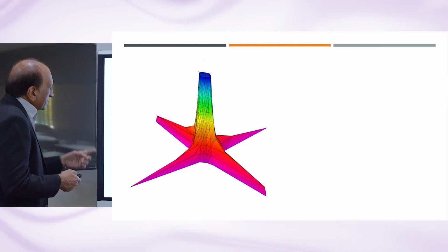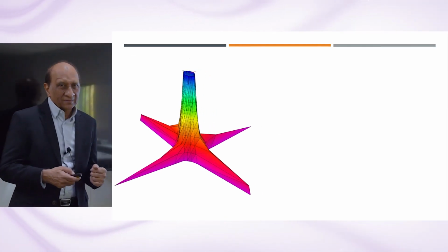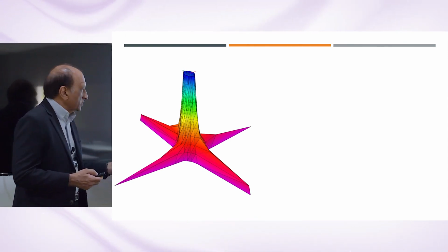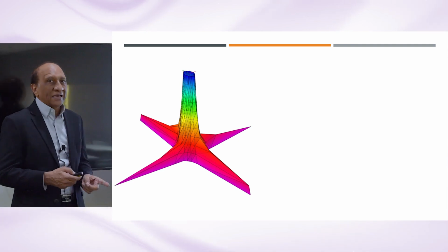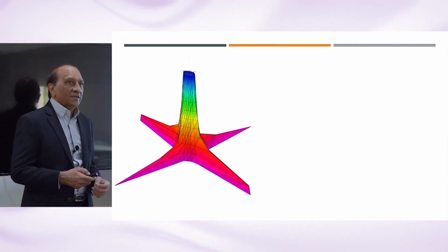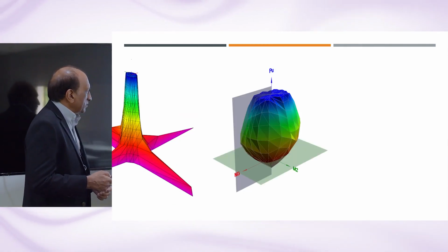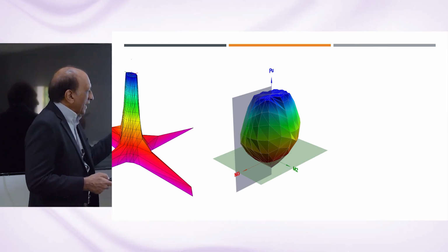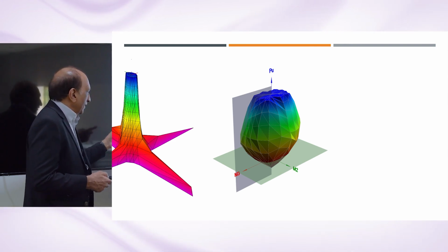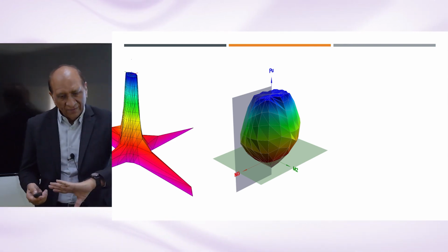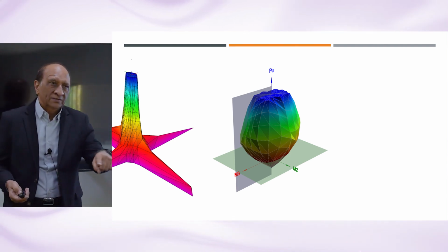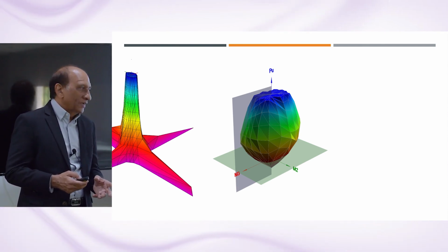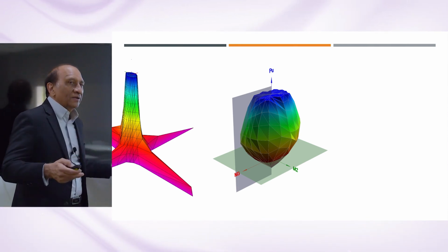And so basically it looks like that. It's a funny diagram, kind of, but it's an interesting one because it shows a lot of information. First of all, in this one, the vertical axis is the axial load, and the horizontal axis is the curvature, moment curvature. So it resembles the axial load and two moment diagram, and you can see the curvature variation along the cross section in the plan, and also its variation with the axial load. As you can see, as the axial load becomes higher, it becomes more uniform.